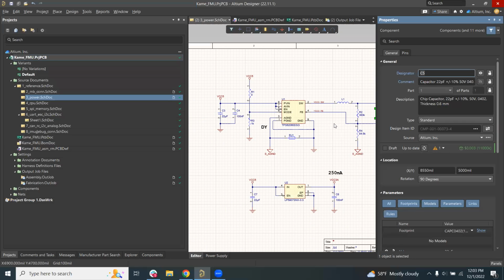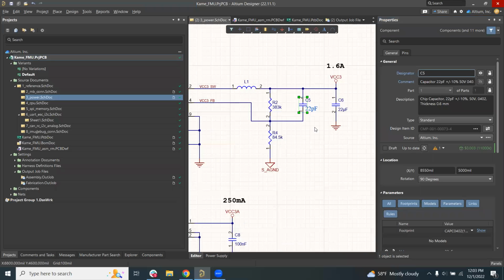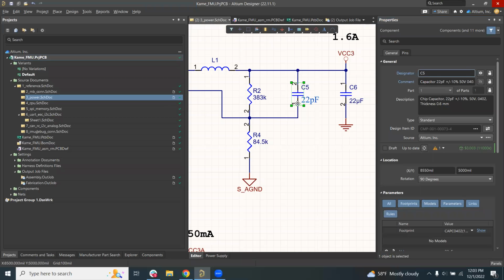A version of that component was released, probably by a librarian in my team, that had updated that revision, but I had an earlier version on my schematic. So when I received that comment from Abe, it was letting me know that that particular component is out of date. There's a newer version of it. I opened it up here just to show that it was out of date. Now I've done that update, so it's no longer out of date.